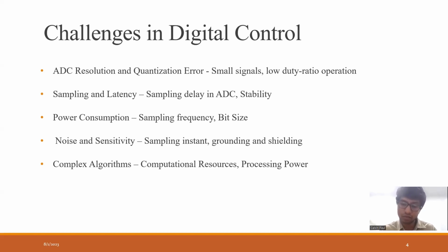Another thing is the bit size of the ADC or the DAC. Assume it is a 4-bit ADC, then it will have a certain resolution. But if it is a 12-bit ADC, then the resolution will be even finer. Even small changes in the signal, it can detect and sense. That is important, but we cannot indefinitely increase the bit size of the ADC. So those are some trade-off challenges which the designer has to consider and take into account.